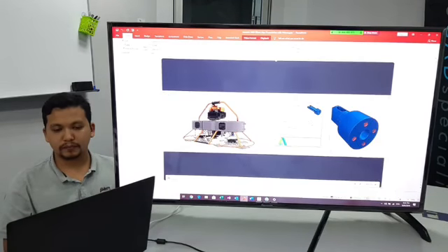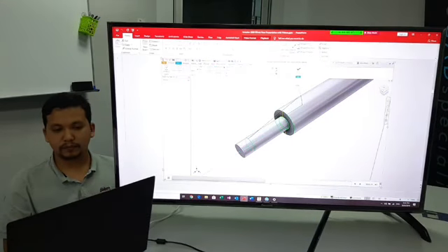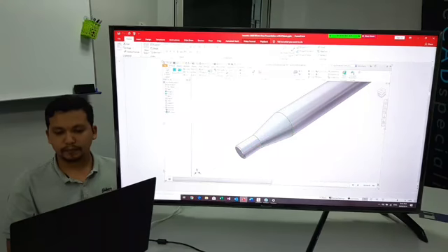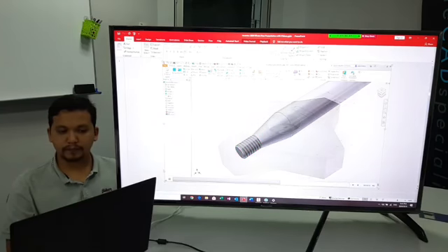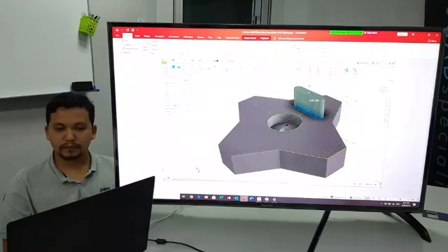Inventor 2020 has also added property panels to the extrude, revolve, sweep, and thread commands to enhance functionality, increase productivity, and give you the flexibility you need when creating geometry. For example, you can easily choose between solid and surface output type, and flip taper angles with the extrude property panel.